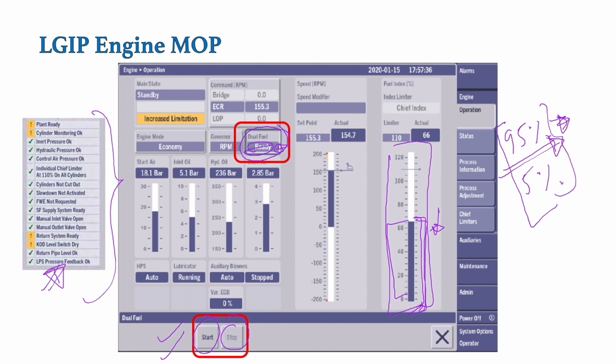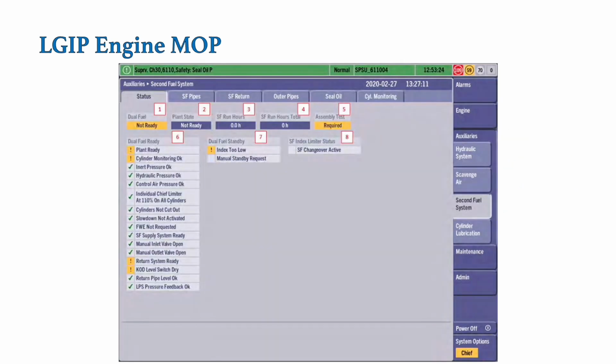For burning the LPG in the combustion chamber, we require a small amount of pilot fuel. This pilot fuel is basically the primary fuel only, but the quantity of this pilot fuel has decreased to 5%, and 95% is the dual fuel. So this is the first screen of the MOP. From the first screen, we can carry out the changeover process of primary fuel to secondary fuel.